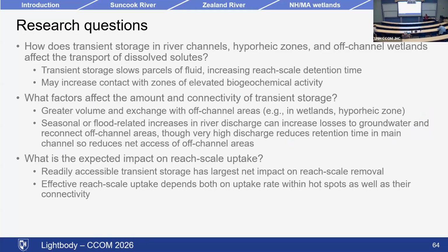It may change seasonally and with flood events. And if we're looking at reach scale uptake, readily accessible transient storage has the largest net impact on reach scale removal and effective reach scale uptake. That's what we see at the reach scale, scaled up to that reach, depends both on the uptake rate within hotspots and also how well connected they are.